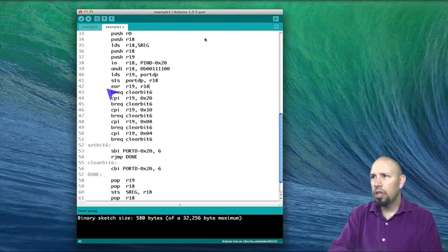Now, when I do this exclusive OR in register 19, I now have what I had previously called Y in my theory. Okay, and so now I'm going to compare immediate register 19 with the value 20. When I do that compare, it's going to see if what's in register 19 is basically this number, which corresponds to having bit 5 set, and it does so in a way that does not change register 19. Okay, it doesn't change register 19, so it leaves it intact.